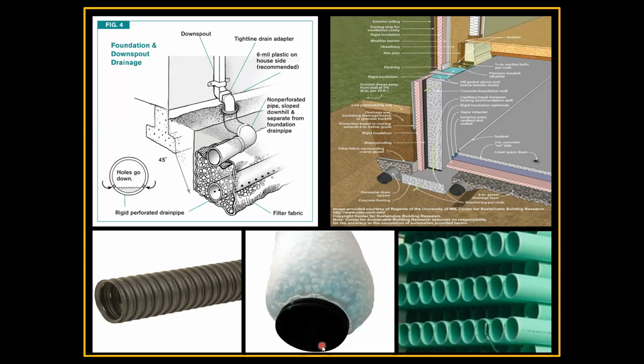And of course, they're using the same pipe here. It's not smooth, has a lot of resistance, picks up debris, and you can't clean it out. You can't run a rooter through it. So this is the Schedule 40 drain pipe. That's the stuff I like to use. I like to use the non-glue stuff, so if you ever have to repair it or anything, you don't have to cut basic sewer pipe.